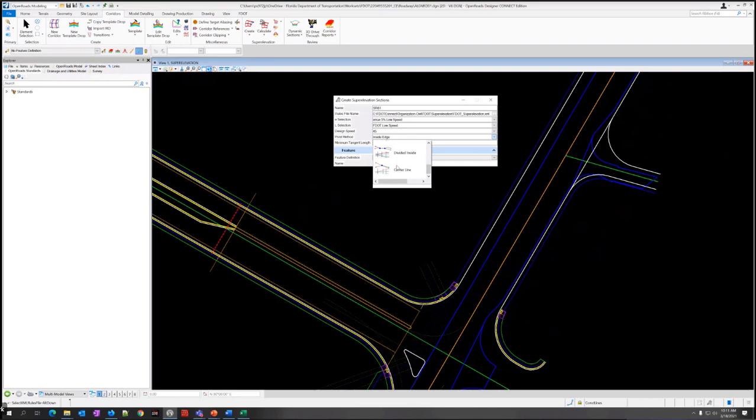So even though ours is divided, we're basically using crown or center line. Center line is really the same as crown. You can see the illustration there. Not much difference. So per the manual, we're supposed to be using inside edge. I think that's based on the FDM for this. Everything rotates about the inside edge. So I'm going to select the inside edge.